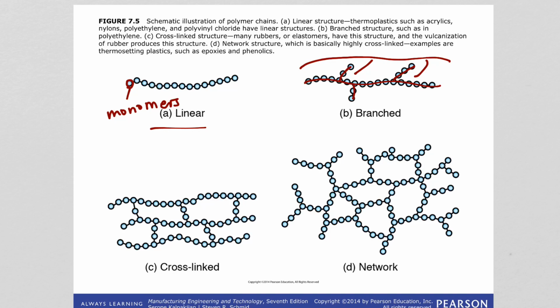So when it comes to cross-linked chains, these are usually for thermosets, rubbers, and some elastomers also have cross-linked structures. What happens there is the chains themselves are attached to each other, not with weak bonds, but strong covalent bonds. So each chain does not slide over the others easily, and that affects their deformation. They are very strong. Okay. But once the structure is cross-linked, there is no turning back, meaning you cannot break those links and get an easily flowing structure.